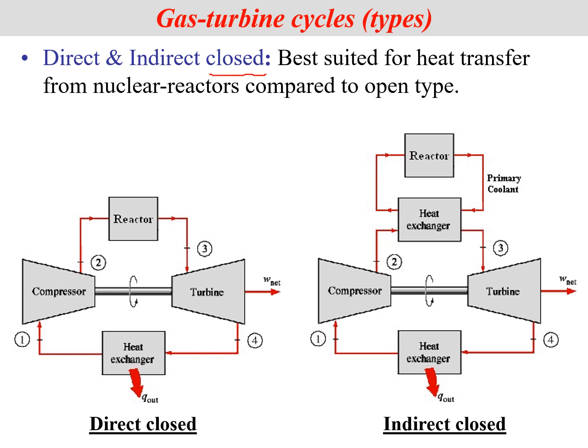After that, we have a third category, that is a closed type gas turbine. Okay, closed type gas turbine, you can most commonly see like this: the vehicle engine cycles, although they are open cycles, you take fresh air and fuel, you compress it, you burn it, you take power out of it and you just exhaust them. But to complete a cycle, to study that IC engine, you sort of connect this exhaust and this intake and you sort of assume that there is a heat exchanger.